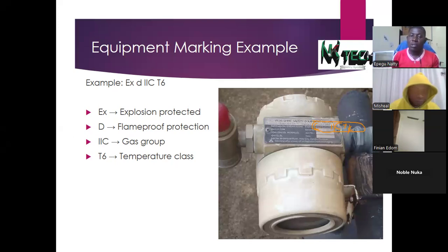So it's also safe because this equipment is meant to detect gases. If there is a leak, it's meant to detect any gas. Now, if this equipment is meant to detect the gas, and by the time the equipment is hotter than 100 degrees, it's going to cause a flame. So you need to select an equipment that will not cause any explosion, which is why they use this particular equipment. So understand that this is something very practical. This is how they select the kind of equipment that they place in a particular place.